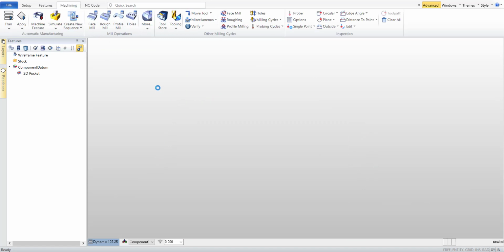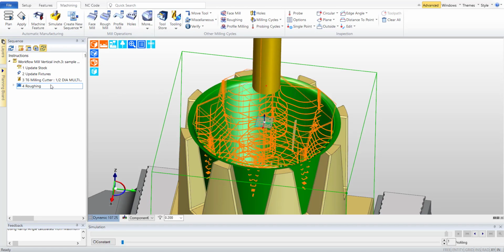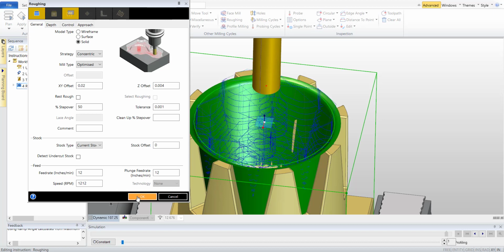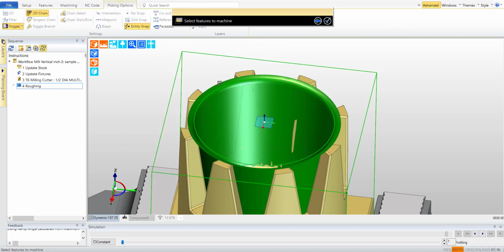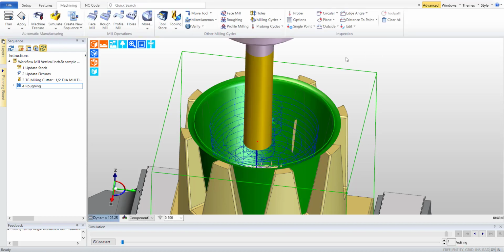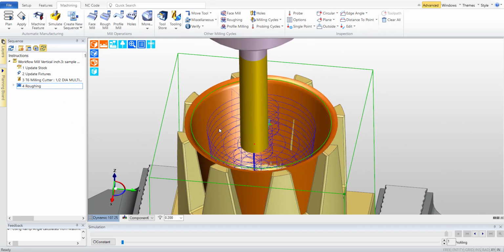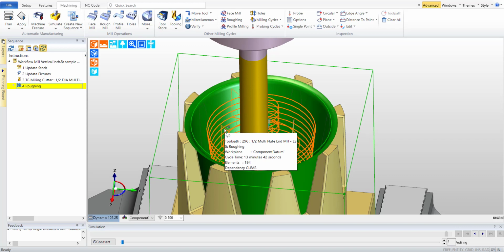Now if I go back to the machining, I want to reselect my geometry here. Again, if I hover over, we get a cycle time of that 17 minutes, 31 seconds. And basically all I'm going to do is reselect my picks. And instead of picking the solid, I'm going to pick the feature that I created with no containment boundary. And here you can see I get a nice continuous path. And if I hover over this, you can drop that down by almost 4 minutes.